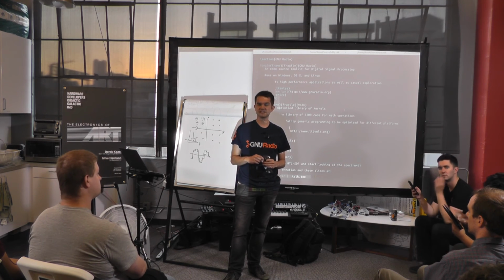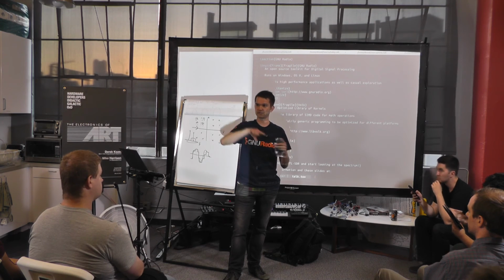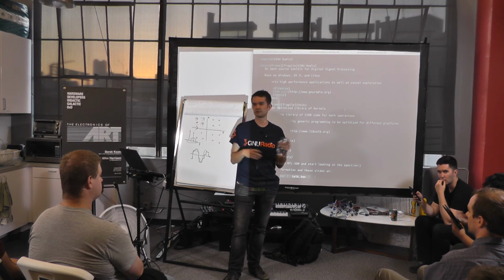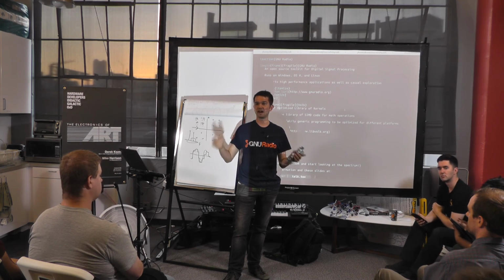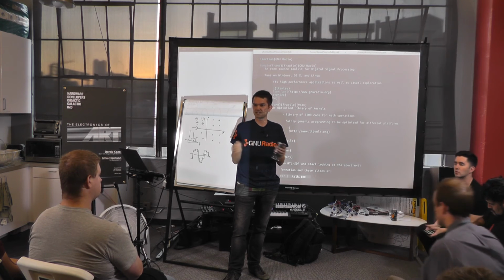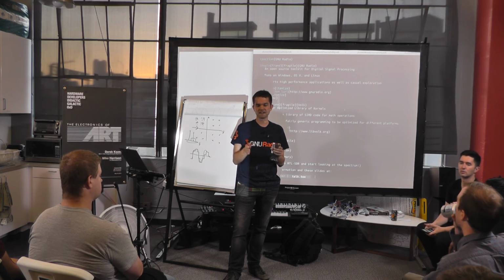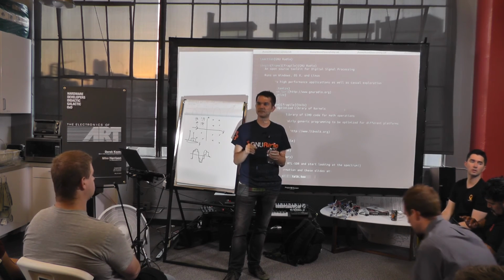As a matter of practice, a lot of the long-range communications happen at low frequencies because they'll actually bounce off of the atmosphere, so you can reach from here to the UK quite easily. If you want to do high data rate, though, there's a fundamental limit based on Shannon's theorem, defined by a professor, on how much information you can pack into 1 hertz of spectrum.